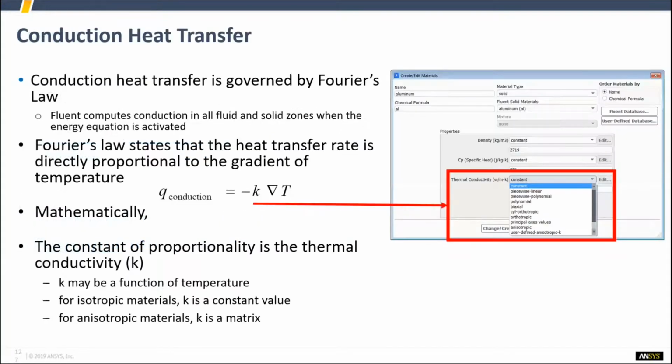Now, when we want to understand heat transfer, we've all been through this in our engineering. We've got conduction, convection, and radiation. So if we want to do a heat transfer problem in CFD, we need to make sure that we're modeling conduction, convection, and radiation where appropriate accurately. So conduction is the first one, and we are looking at our Q value. We can put that in our thermal conductivity for our material. Okay, so generally it's going to be our solid material, and that'll come up when we turn on energy equation.